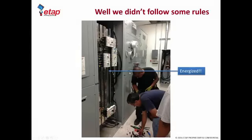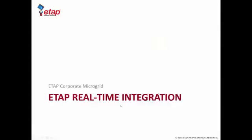Now, when we talk about energization and working on equipment, one of the things we always talk about is arc flash. We were on a time scale to get the work done, so some of the work was done energized, but typically you would do this with hot gloves and appropriate PPE. In this case, you can see these two gentlemen actually adding a new circuit breaker onto a live bus, but using hot gloves and wearing appropriate protection.